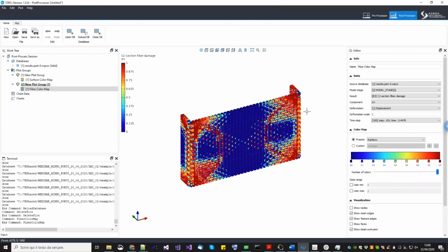Now, in finite element method, there is one basic assumption that the displacement field should be sufficiently continuous. That was one of the basic assumptions of finite element. The problem is that when we use strain softening material, we are actually introducing discontinuities. The strain field is not continuous. In fact, you see that the deformations are completely inside the thin mortar layers.